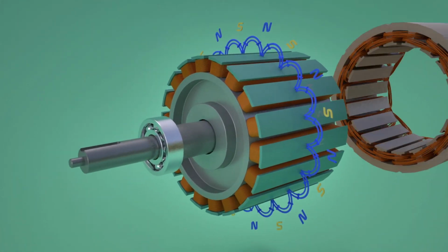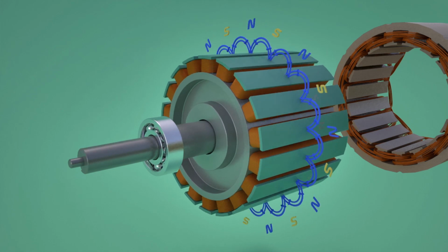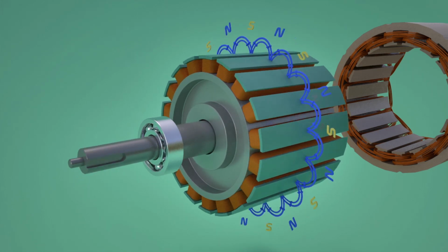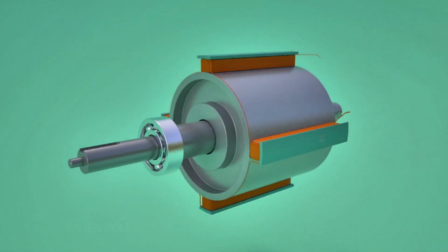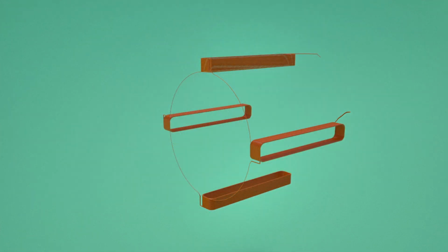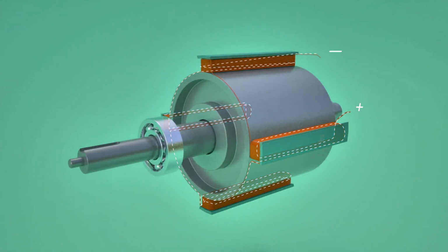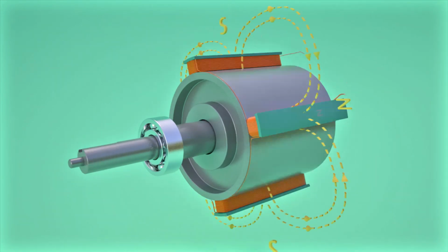Rotor produces a rotating magnetic field, armature coils are stationary, and rotating magnetic flux associated with the rotor induces electricity in the armature coils. For better understanding, let's consider a rotor with just 4 poles. Rotor coils are excited with a DC power source. Magnetic field produced around it would be as shown.